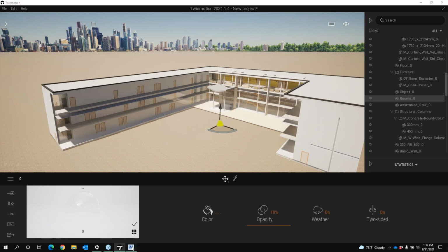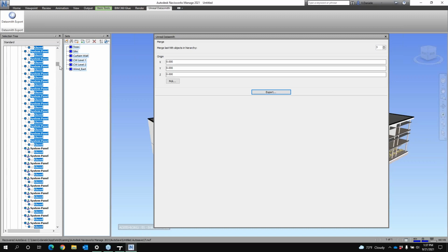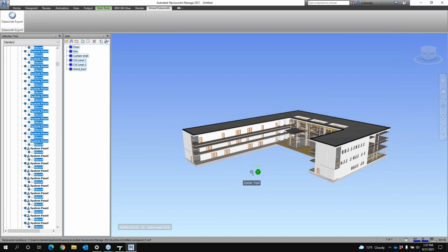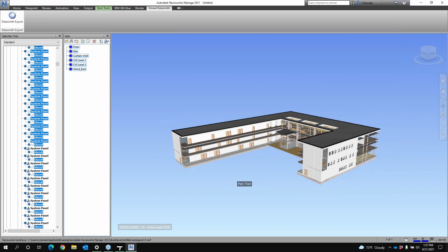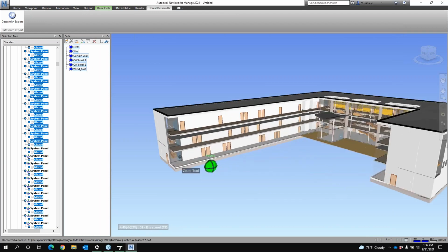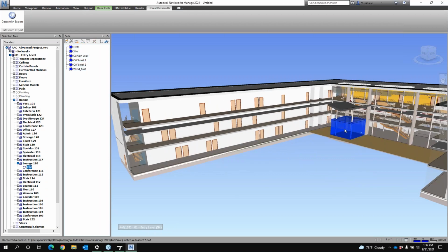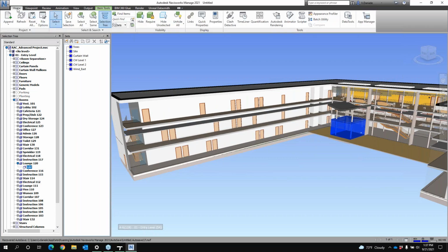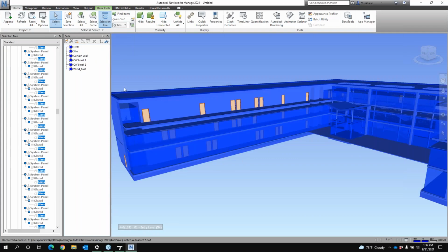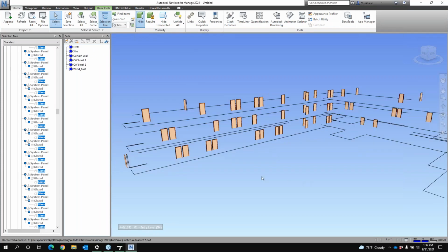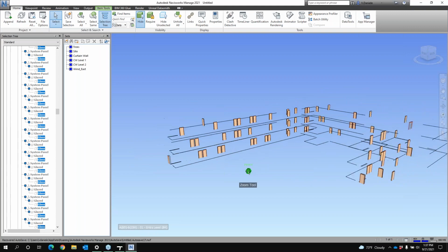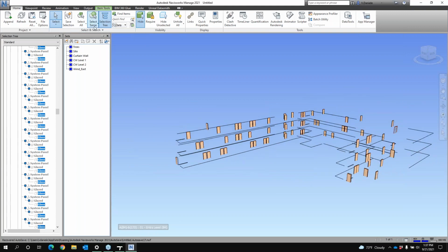So one thing you would want to do in Navisworks is find those rooms and probably just delete them out of the Navisworks model, or hide them, because you can see there's some weird room objects in here. So I would probably grab that from Navis, select all the same type, and just hide them. You can't delete, but make sure you would hide the room objects.